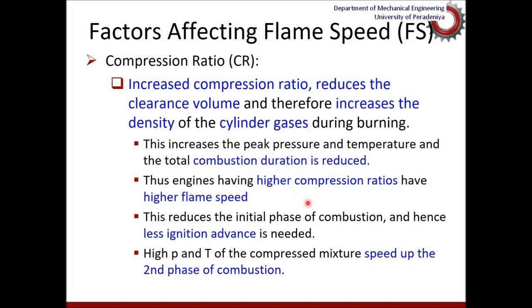The higher the compression ratio, accordingly, the higher the flame speed will be, and that increase of flame speed would reduce the initial phase of the combustion process.